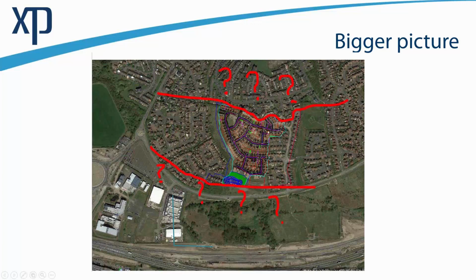North is high and south is low, and our development is kind of in the middle. So just to understand how the new development affects the existing catchment, we will only import MicroDrainage, we will create a grid, and we will run the model, and we will see how it runs off. But to understand how the upper side of the catchment affects the existing developments, we will introduce something called rain on grid.